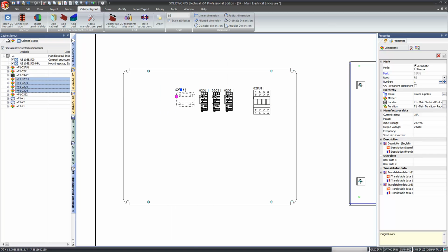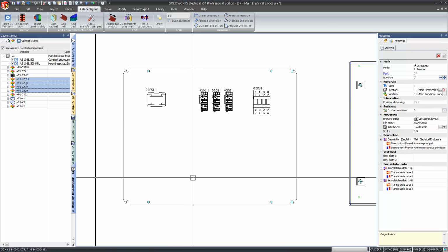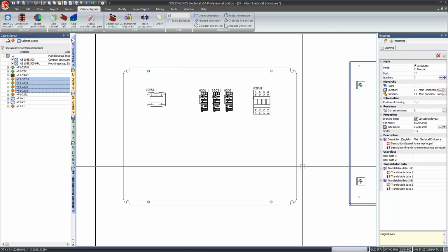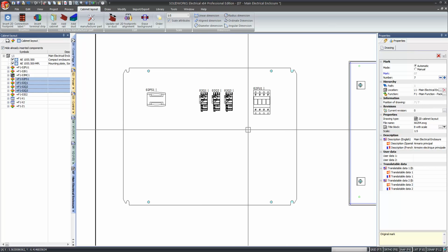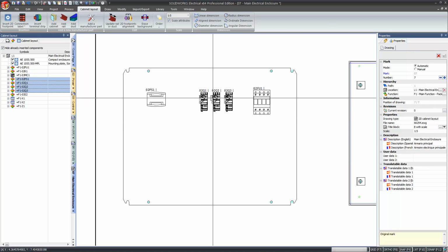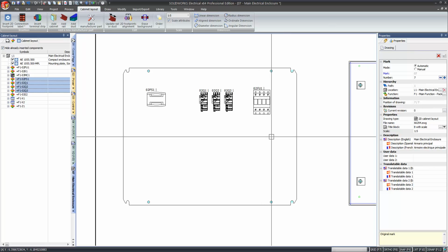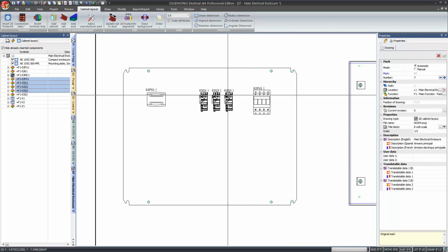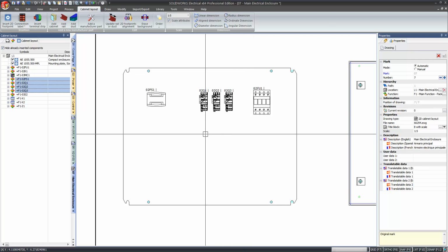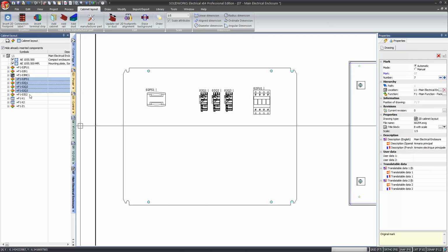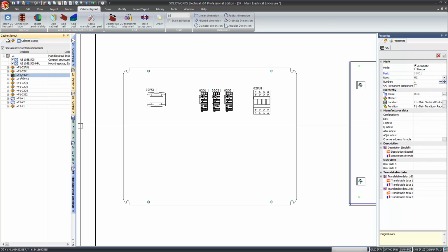And I'll just drag this guy a little off to the side though. I want the power supply to be at the edge. And the idea is since I'm kind of limited for space vertically, rather than putting the circuit breakers right here below the power, where I'd have power coming here and then coming out into circuit breakers, I'm gonna have to reroute my cables up like that. So I'll put a duct in there and I'll fix all that later. But what I'm gonna do is set up the basic layout and then move from there.